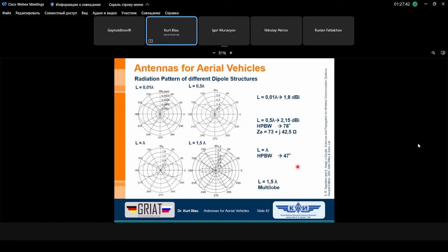If we want to have a gain equivalent or gain normal, we can use the half wavelength long dipole, and then we can assume these values. It's very simple to realize, and we can achieve very good measurement results with this dipole as a gain normal or gain equivalent.